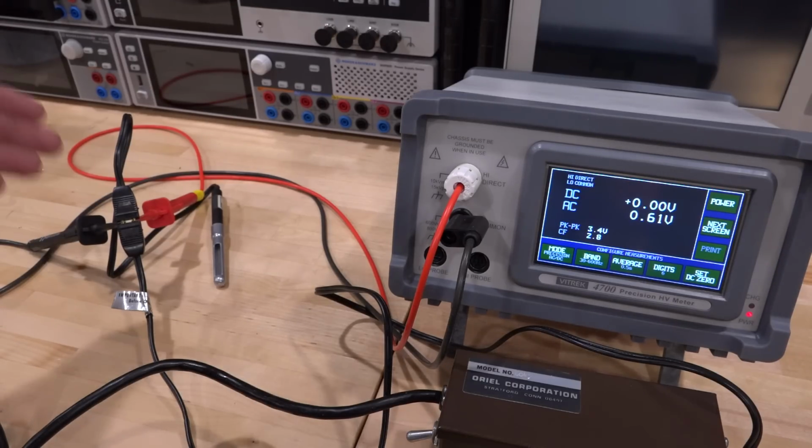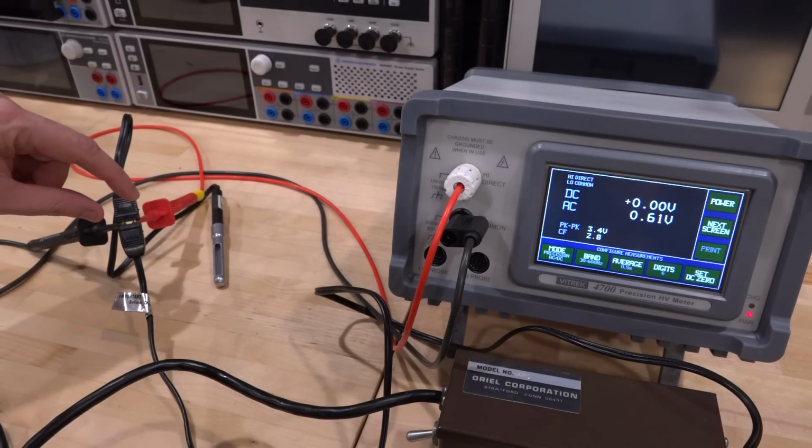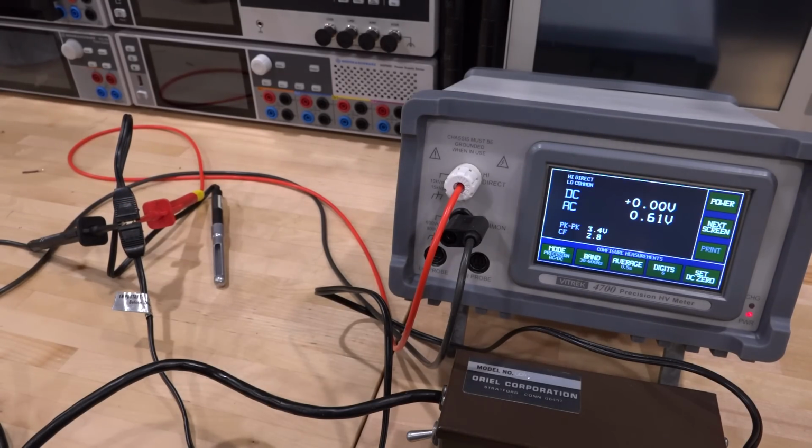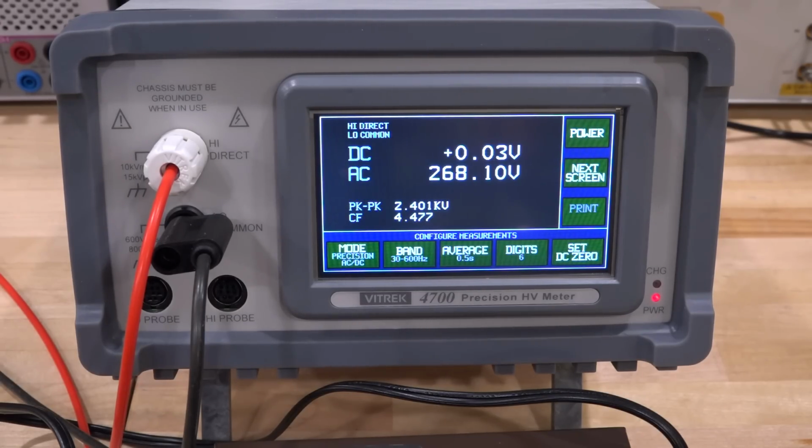So same situation, except that now the tube is directly connected and we're monitoring across the terminals of the tube. Turning it on, look at that, we're getting only 268 volt RMS, but the peak to peak is like 2.3 kilovolt, and the frequency comes and goes, and there's even a little bit of DC. But this is an example of how self-regulation can happen using a transformer if you don't care about the shape of the waveform at all.